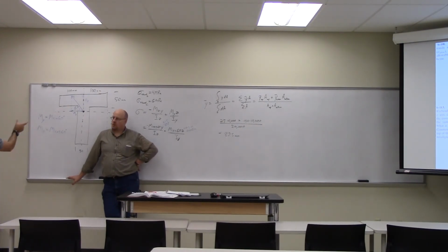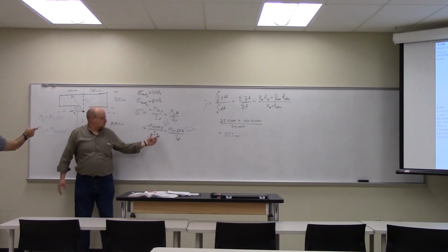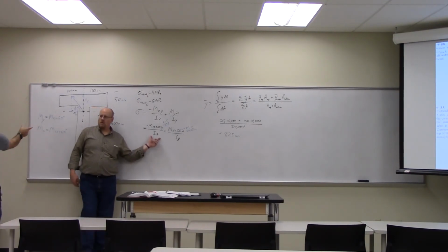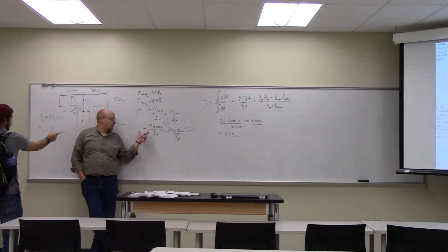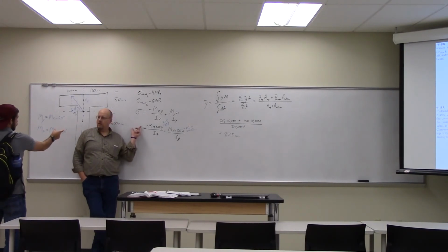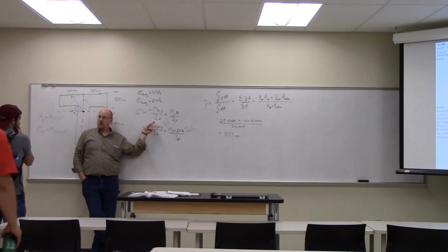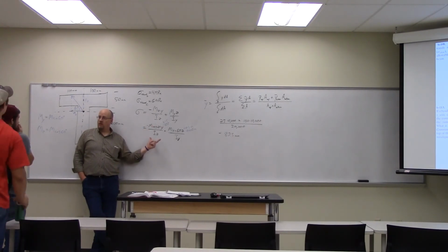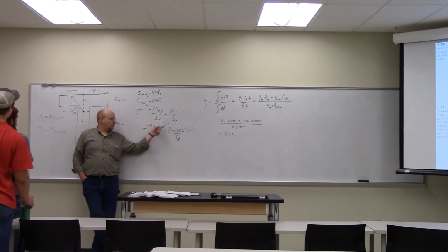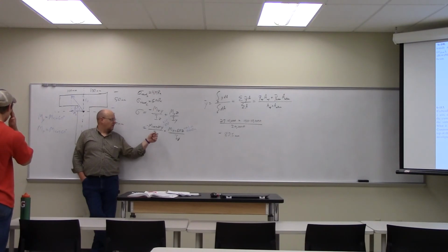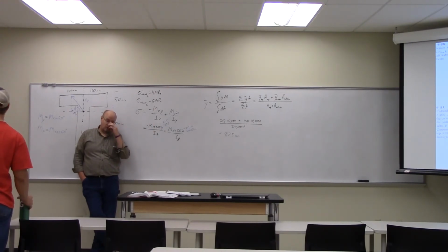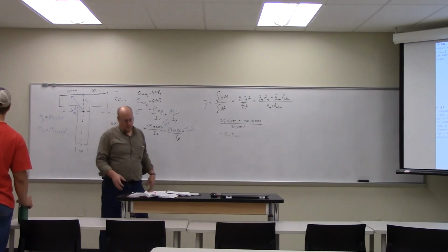Now, moving over to the left side of this equation, over on the other side, that's just sigma in general. So we'll plug in the top set of coordinates and find the compressive stress. And then we'll plug in the bottom set of coordinates, or vice versa. Anyway, we'll plug in one set and find the compressive one, and then whichever end is the most is our answer.